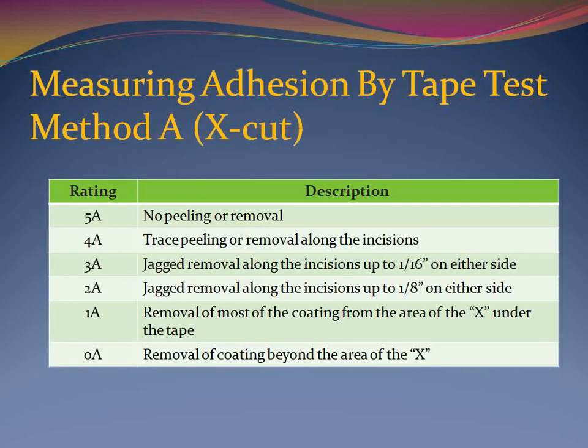If possible, the location of break should also be recorded as adhesive, which is a split between 2 layers or between the substrate and the first layer, or cohesive, which is a split within a single layer of coating.